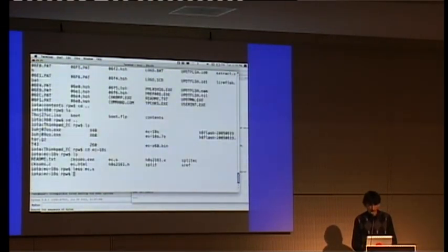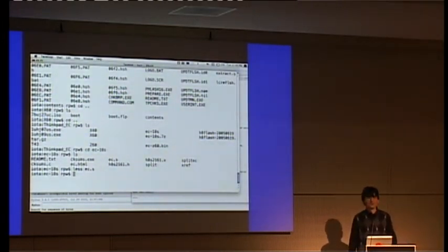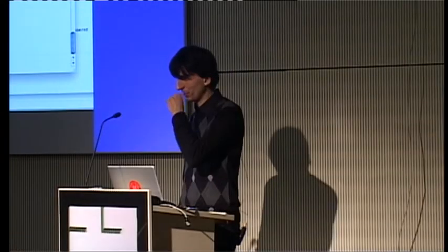Once you've done this, you need to correct checksums. So the old utility for computing the checksums from this source equivalent distribution still works, and the tool chain for compiling the firmware. There's a version of the GNU binutils for this architecture, so you have a nice round trip. You can disassemble, correct what you want to see corrected, and then build it again.